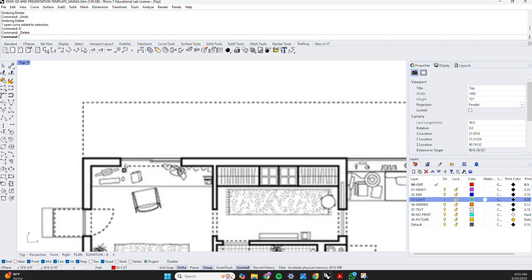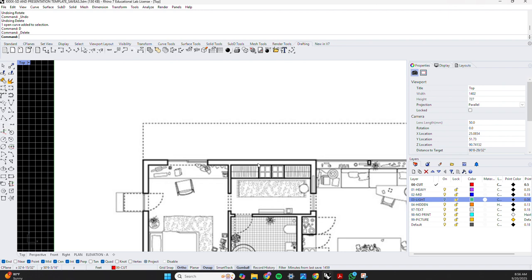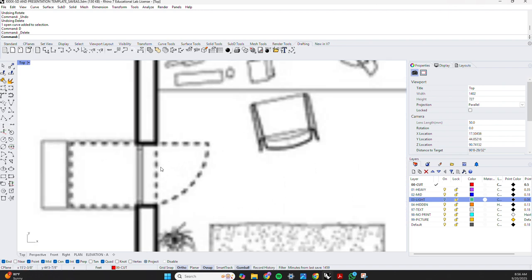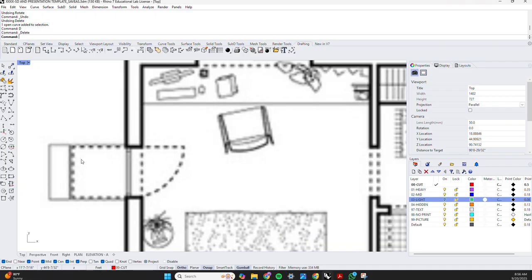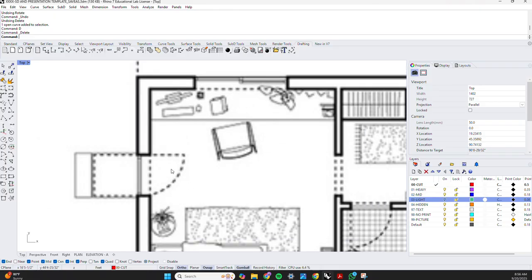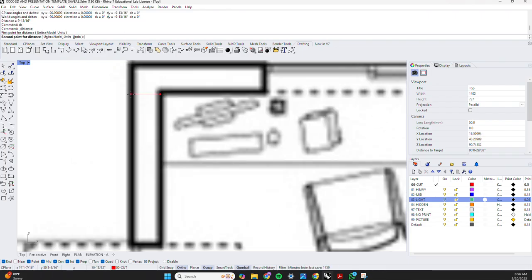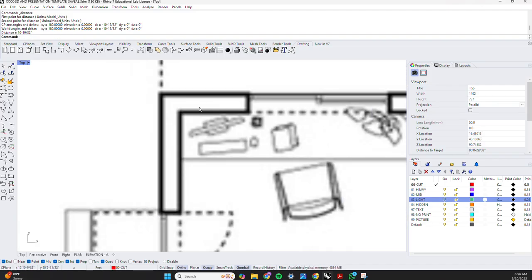It's a framed building in a climate where I expect the walls to be about 10 inches thick overall, and often on residential projects, 3 feet is a somewhat typical width for exterior doors. So that is what I set this to. I thought I had this at 10 feet, or 10 inches. Yes, and so that's actually a great example of what I'm talking about here.